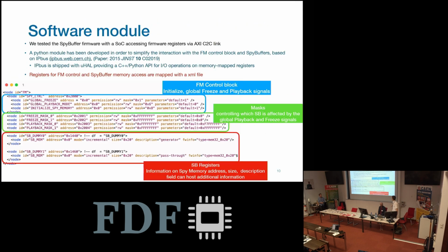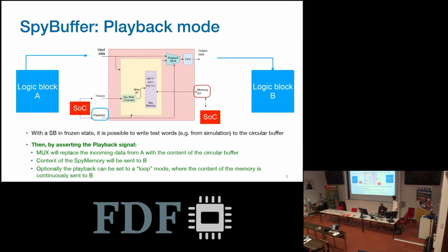If you go to the block diagram of the, even the Atlas one or the main one, so if, you mean this? Yeah, maybe. So if I show you the block diagram of a JTAG controller, right? It also has a data bus, it has an instruction register, it also provides features to stop, halt, freeze, and playback, right? Plus JTAG is an open source specification, right? That each vendor, of course, like vendor specific people do it their way. It's also a fast bus.